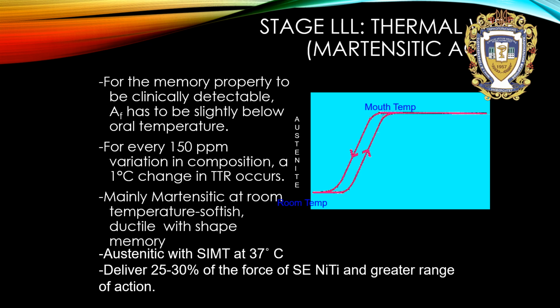For every 150 ppm variation in composition, a 1 Celsius degree change in TTR occurs. Mainly martensitic at room temperature, soft, ductile with shape memory.